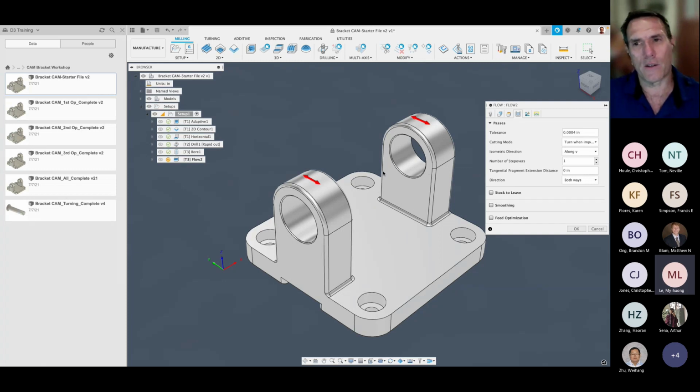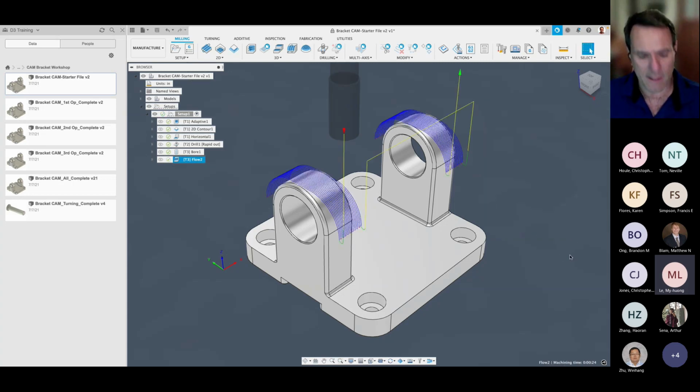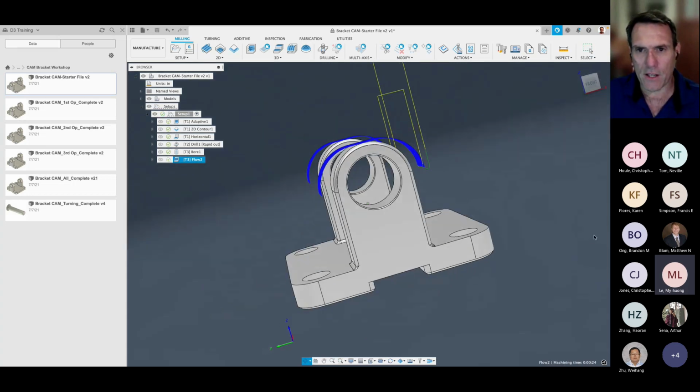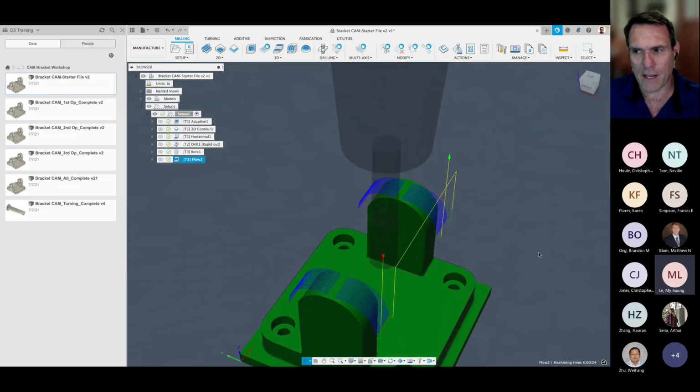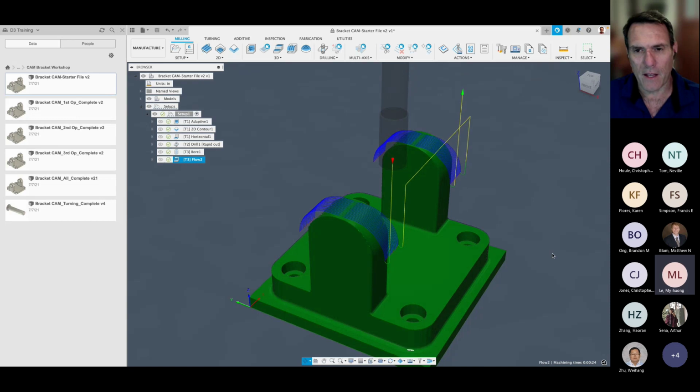And this particular solution is just going to go back and forth along the tool path. And right now, one step over isn't going to get me much. So I want to change this value to 20. So on each one of these faces, I'm going to have it step over. It'll divide the width of that face by 20 and just go back and forth over the part, just like that. And you'll see the curvature that's created because, oops, I forgot to change my tool.